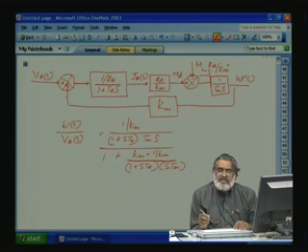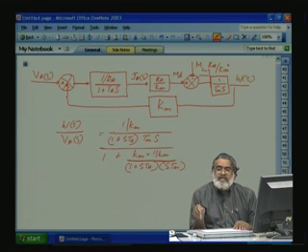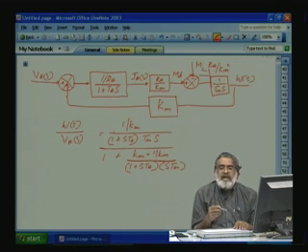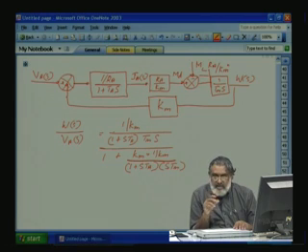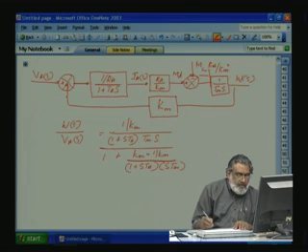So, why is it required? If you know the time constant form, we know which time constant is the largest time constant. So, that will delay the system. If I use a PI controller, the 0 of the PI controller can be chosen such that this large delay can be cancelled. Delay means there is a lag, it will introduce a lag. The moment you give a 0 it will give the lead. So, this lead and lag will try to compensate the total delay of the system, that is the purpose.